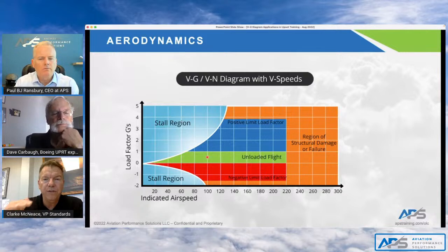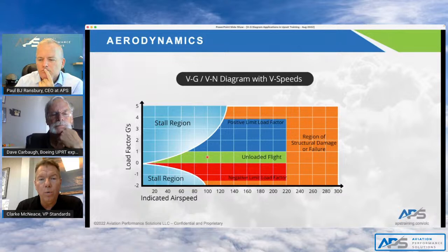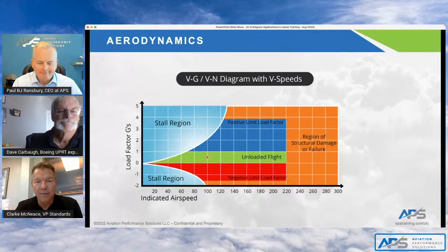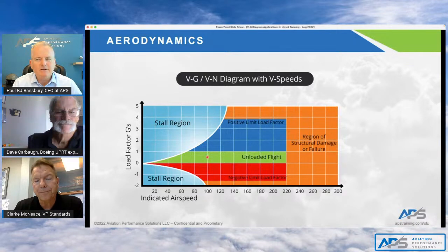When you feel less than 1G, when you're light in your seat, you are still positive G, but you are not negative yet. Now, you know when you're at negative G's in an airplane by the fact that you are out of your seat and up against your straps, your coffee and your iPad have hit the overhead, right? Now you know you have overpushed. Yeah. Except for an extremely unlikely situation, it is highly unlikely, if not never, that you're going to go to negative G as the appropriate technique in an airplane upset event.